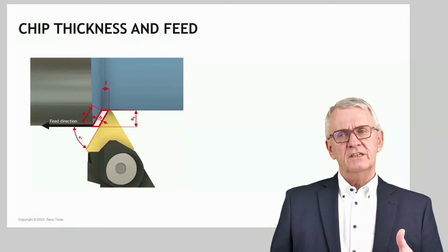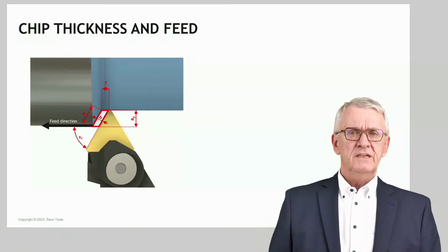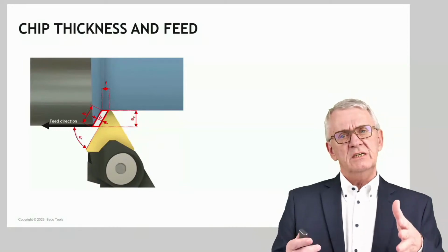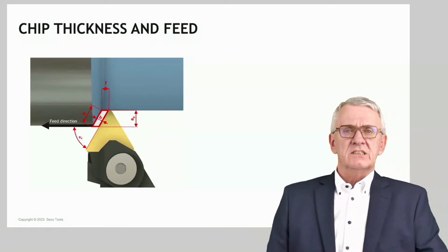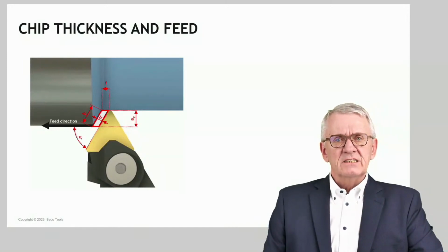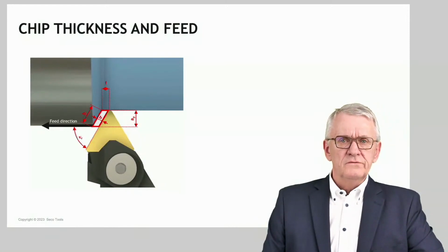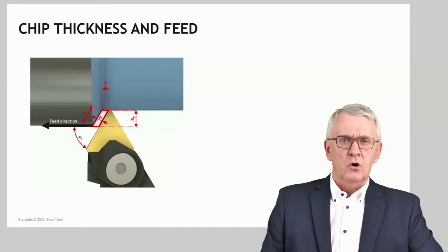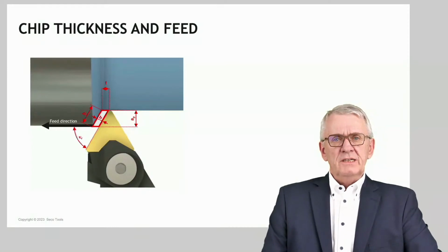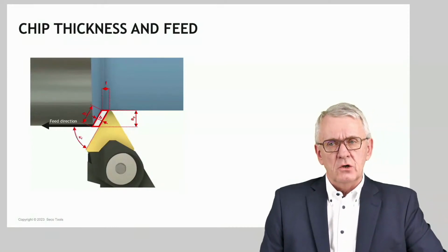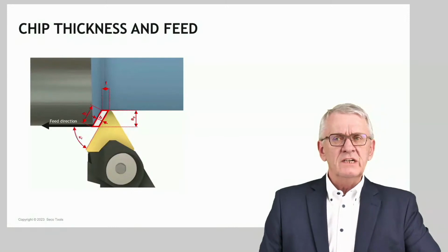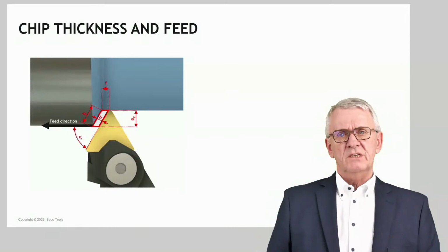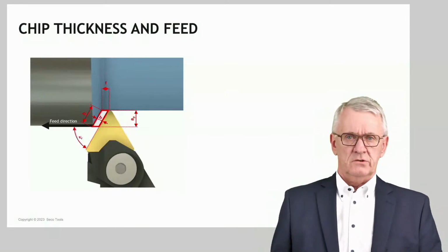Because if you listen to the definition, take for instance the feed. The feed is the speed with which a cutting tool moves along the workpiece. So it seems that the workpiece is the reference. Feed is how fast a tool moves along the workpiece. Depth of cut is the thickness of material I remove from the workpiece. The cutting speed is the speed with which the workpiece rotates in case of turning. So it's all about the workpiece. Those cutting conditions we refer to as workshop cutting conditions.